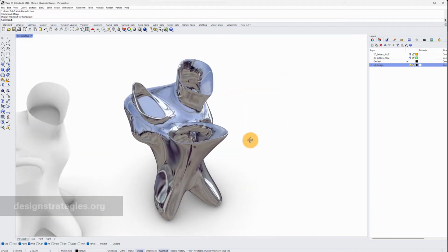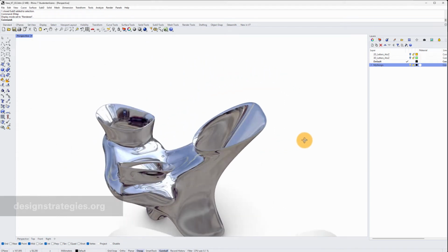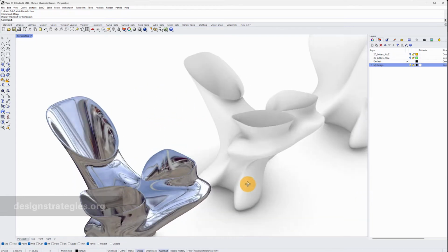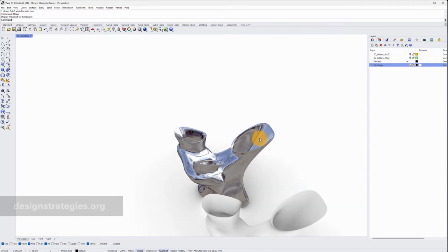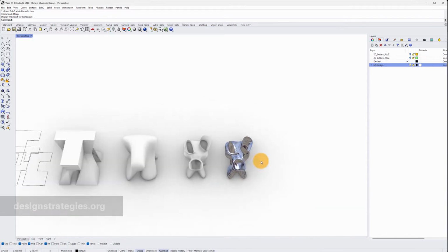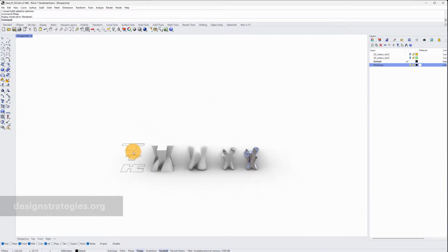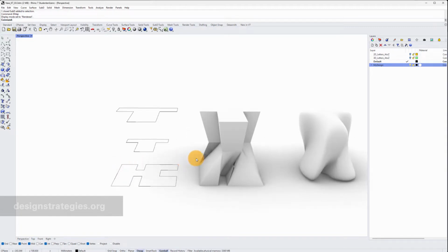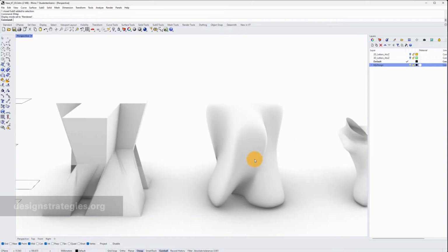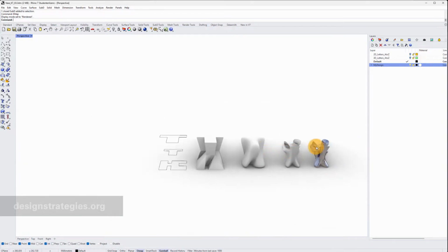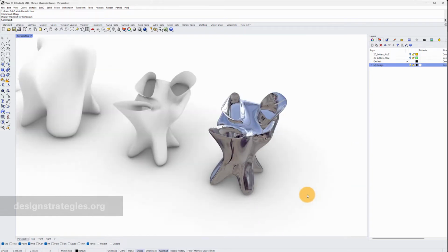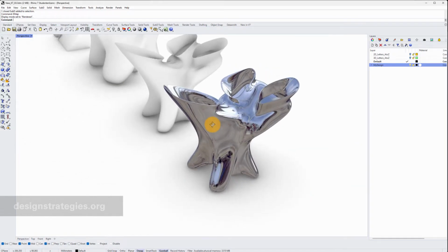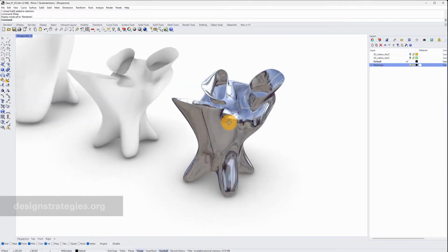This video is an introduction for subdivision modeling in Rhino. It is a small design exercise which ends up in a model which can be 3D printed. It's based on lines, on curves. These curves are extruded with the loft function, converted into a sub-D model. In subdivision, it is modeled, has some transformation, and ends up at the end of the day in a printable 3D object like you see here right now.